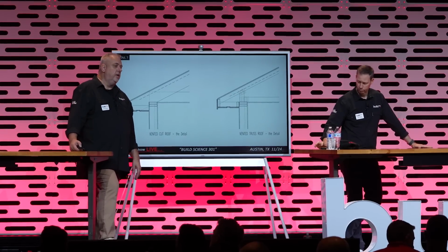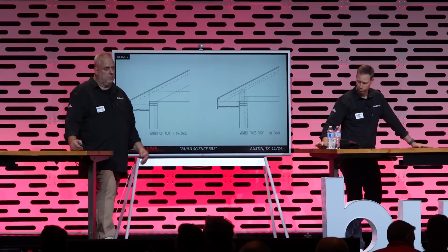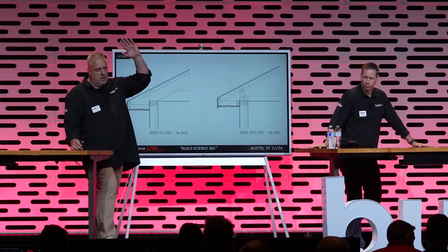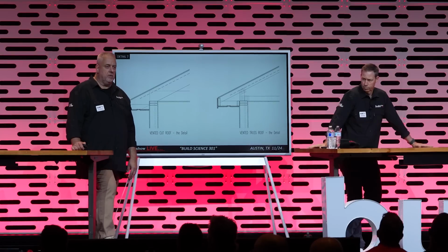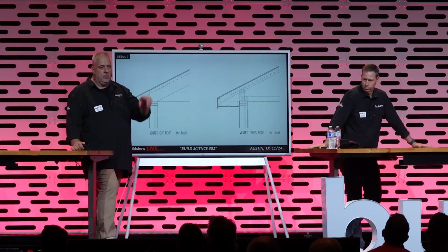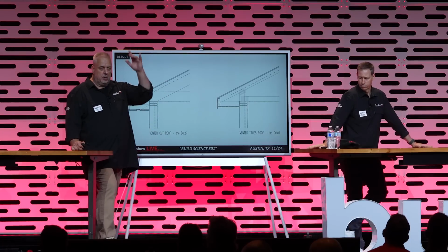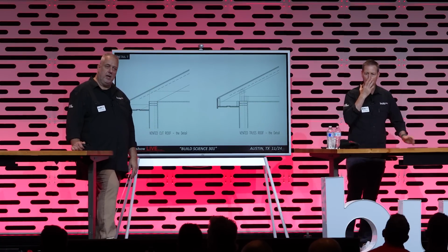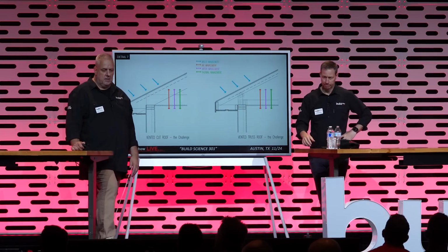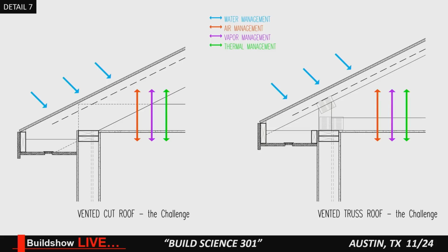And he's taken this house to zero energy, and the air tightness has gone from like 30 plus air changes to passive house levels. So, vented roof, pretty simple one, right? Put a vent in, goes up, takes air up into the roof, moisture migrates through the roof assembly, moisture goes out the ridge vent, right? Pretty basic physics, right? There's their challenges.